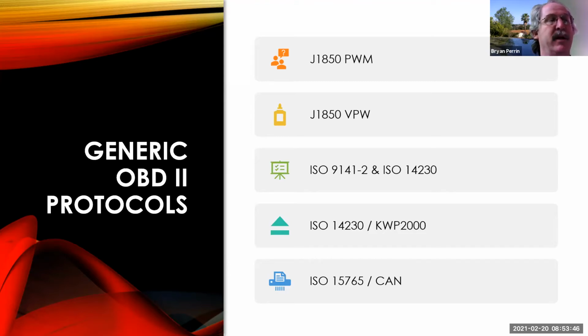Now there can be other, and there will be other CAN systems on the vehicle that may be even connected to the DLC. There are several CAN systems that will not be connected to the DLC. They are not necessarily going to follow these protocol rules. They're not going to follow necessarily these bias voltage rules. They may not even be 2-wire, depending on the speed of the CAN system. But fortunately for us as diagnostic guys, as of 2008, with the exception of 2 models, the Chrysler Crossfire, and I can't remember the other one, everything 2008 and newer under 14,000 pound GVWR is CAN.